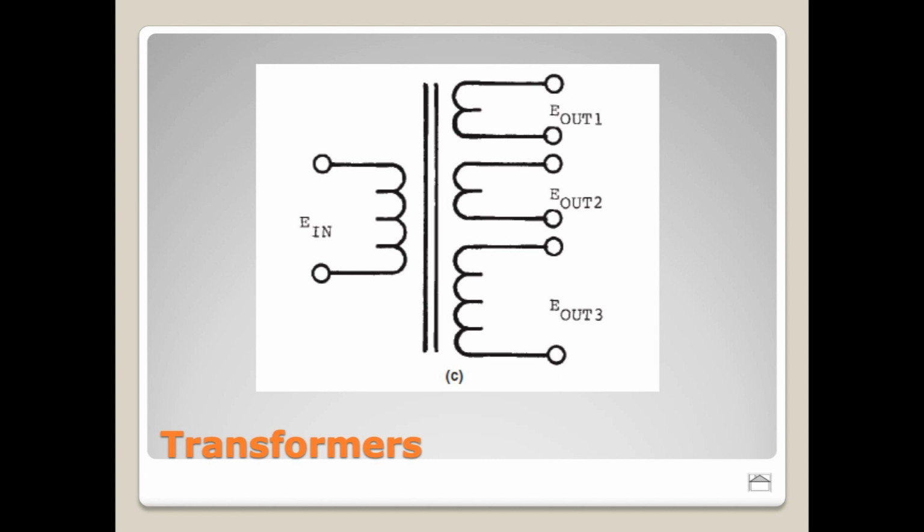Then we have to actually design it to do that job. And then once we do the design, we have to figure out exactly what the power requirements are. And then we design the power supply around that, and then the transformer is designed specifically to drive that power supply. So this really is something that is custom made in many cases when we're talking about power supply transformers.